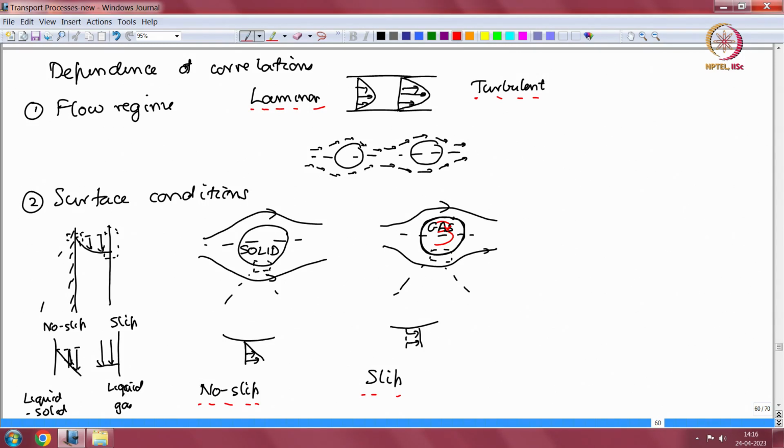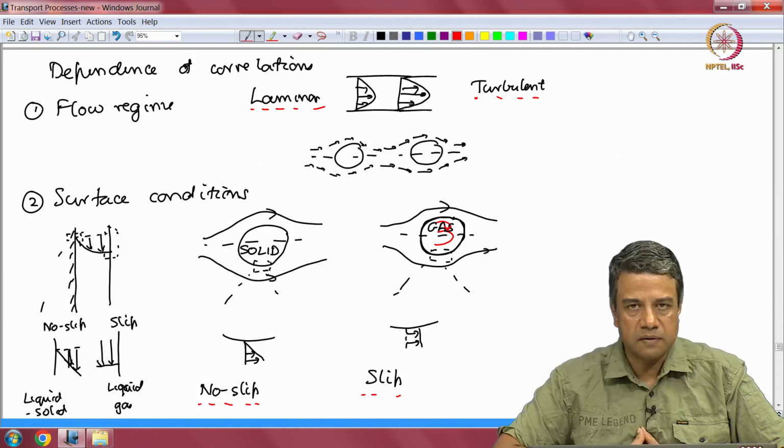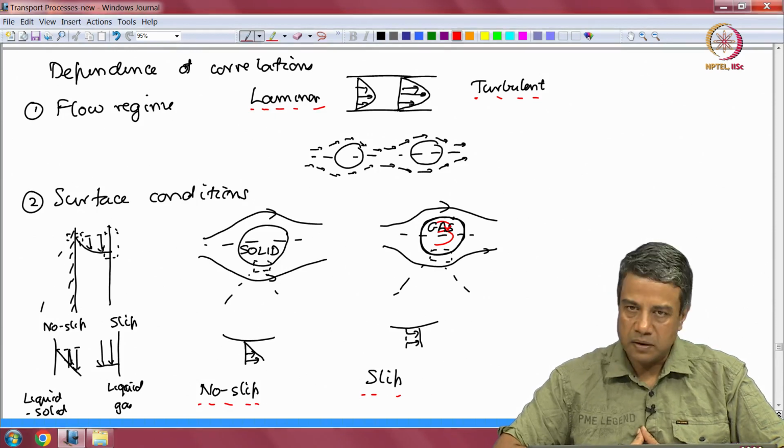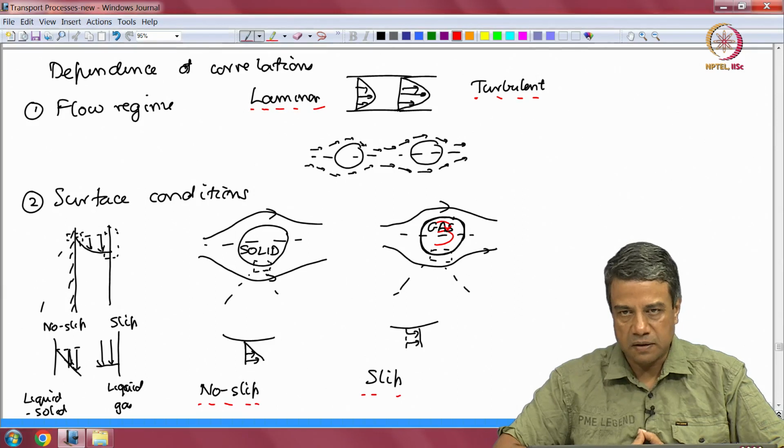In the flow through a pipe, the transition is rather abrupt or discontinuous. At a Reynolds number of about 2100, there is a transition from a smooth laminar flow with smooth streamlines and no cross stream velocity fluctuations to a turbulent flow, where there are intense turbulent velocity fluctuations in all three directions, though the flow velocity is on average along the axis.